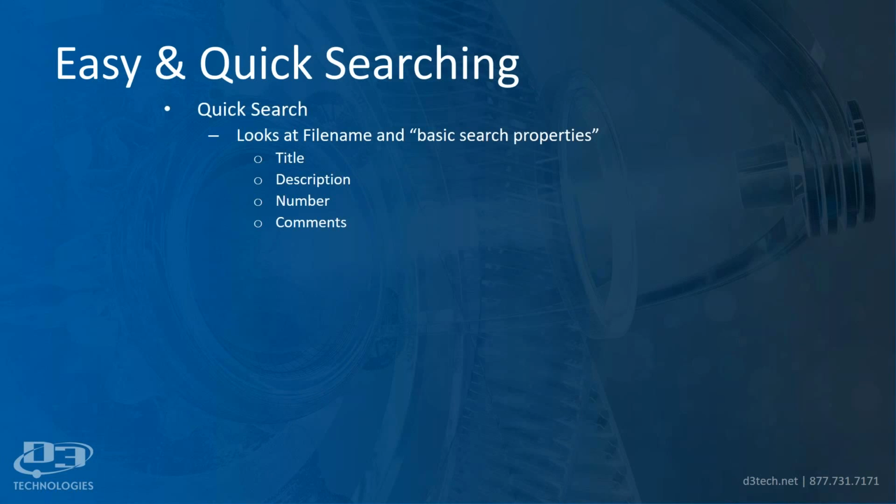So Autodesk Vault helps you quickly search for files in a matter of seconds, along with its version history and other metadata. To make things clear, a version is totally different from a revision. A version is an iteration of a file. Every time a user checks in or checks out a file, that is a version, while a revision history is a file that is going through a particular workflow to get the project manufactured or released. So essentially, Vault keeps track of both revision history and version history.